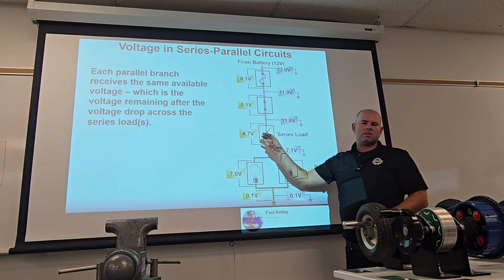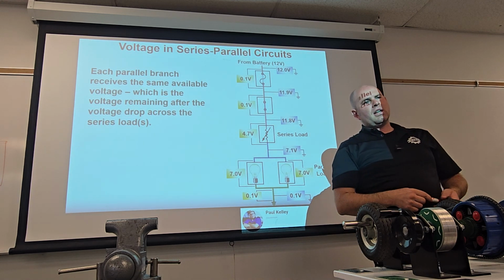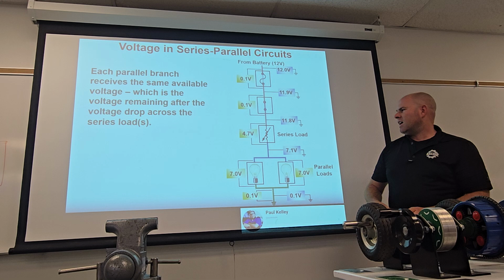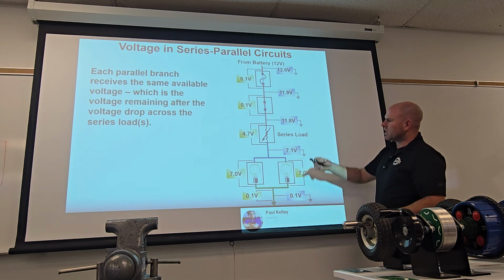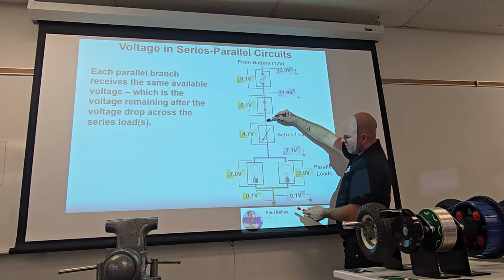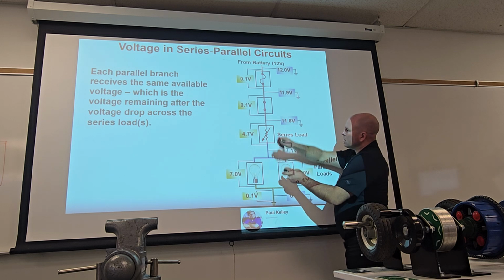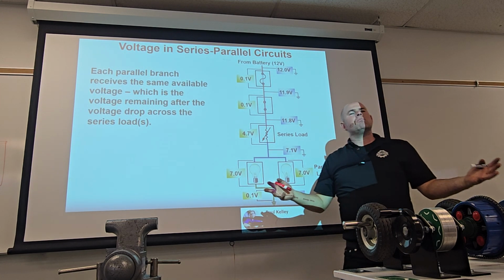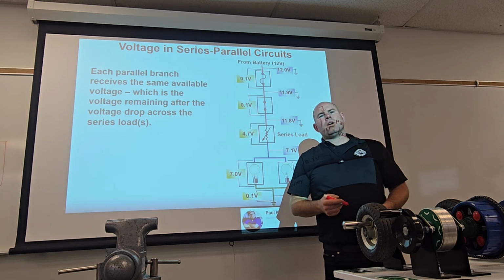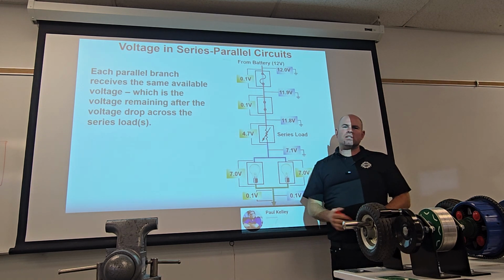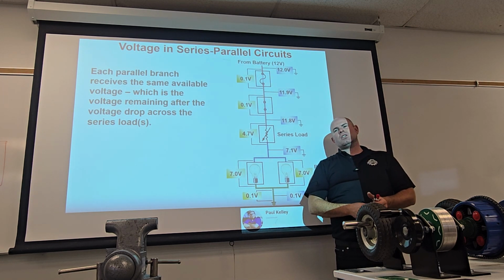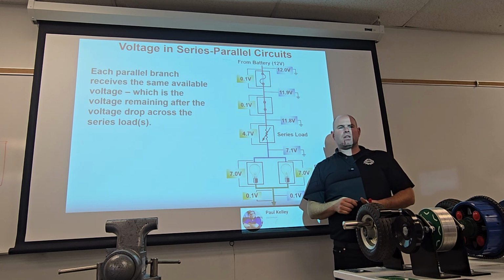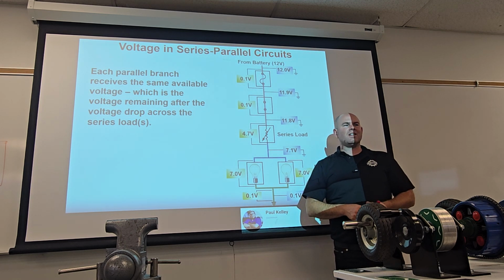Now, if you wanted to test this dimmer, in the unlikely event you're working on an actual series parallel circuit, you could test available voltage. You should have 11.8 or so coming in, and then coming out, you should drop some number. How much? Well, this is a variable resistor. So you guys actually have seen in your circuit building, there is a variable resistor in there.